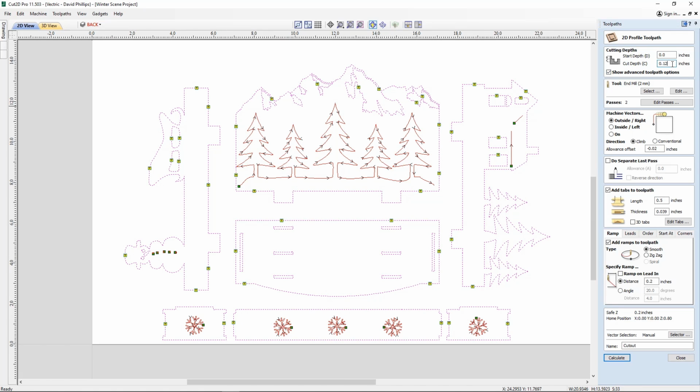So cut depth, gone a little bit past the 0.118 material thickness, just to make sure that it cuts through correctly and we don't have any membrane on the back. Because I'm going to be using MDF, it tends to tear on the bottom layer. Same end mill, 2mm. Make sure that you change this to reflect your tool and settings, and make sure that the feeds and speeds are appropriate for your machine.